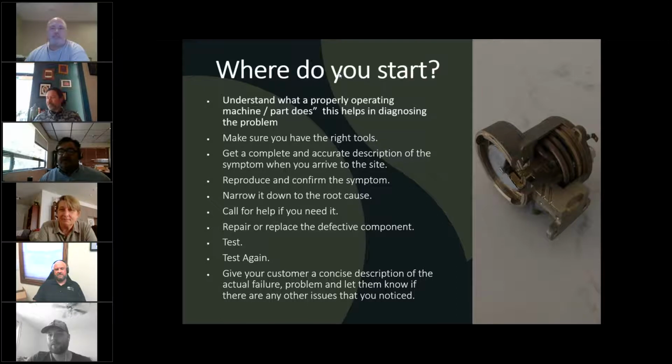Yeah, I think there are situations too where you might have a lot of things you have to cross off. Let's say it's a water related issue and you're having some flow problems. You might check internal flow diagrams and check the entire path of the waterway and make sure it's clear. Then you might think, okay, maybe there's something going on with the back of house RO system or the water filtration. So you go back and check that, and you're not 100% sure, so you pull out an inline gauge and check your water. Those things take time, to filter through, make sure all your valves work, and make sure your water paths are clear.